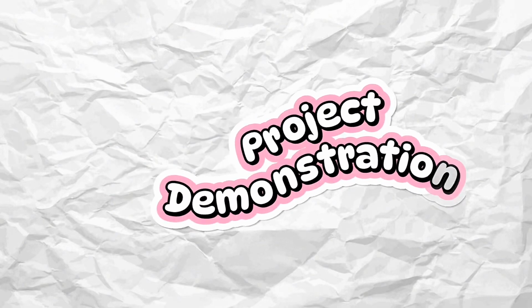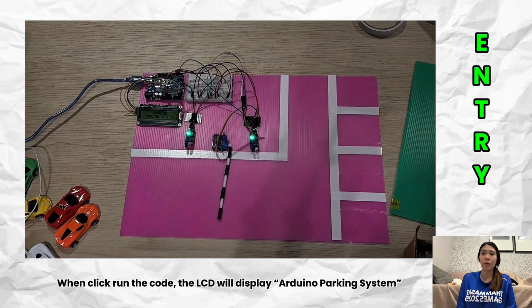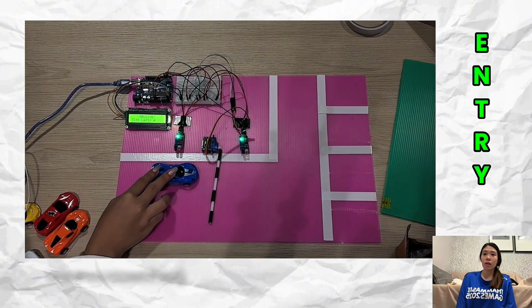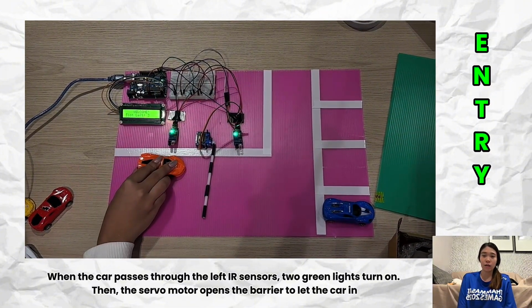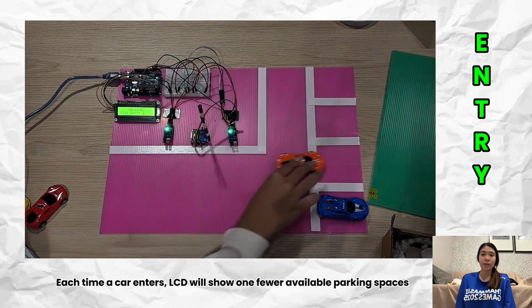Project demonstration. We'll start with entry. When we run the code, the LCD will display Arduino parking system, starting with welcome, slot left is 4. Now, when the car passes through the left IR sensor, 2 green lights turn on, then the servo motor opens the barrier to let the car in. Each time a car enters, the LCD will show one less available parking space.